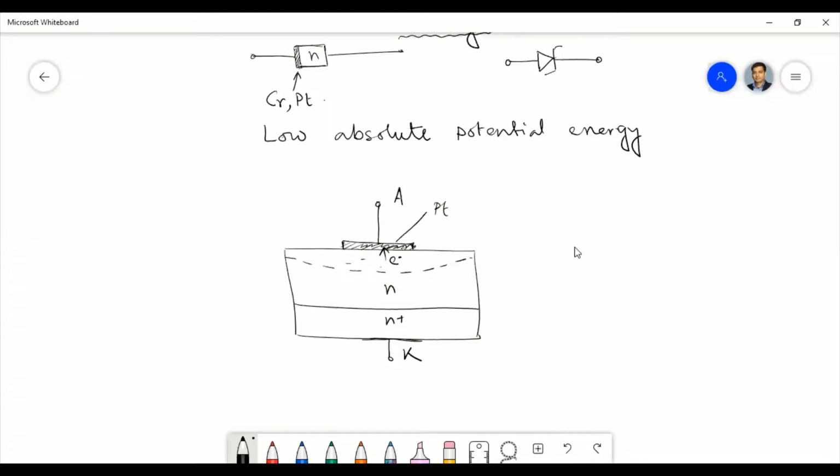As we have seen, in a diode there is a charge storing phenomenon, and charge storing time is required. Here the stored charge phenomenon doesn't occur, so the parasitic capacitance we mentioned for the PN junction is absent in the Schottky diode.